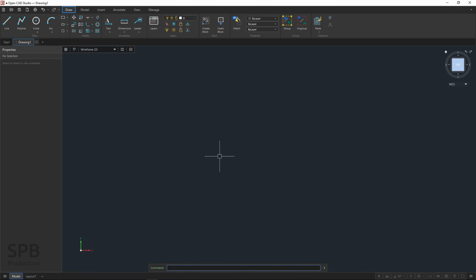Let me first show you, without the polar tracking turned on, if I wanted to create a rectangle from lines, I would fire up the line tool, I would click the first point, and then I would move my mouse and I would enter the distance. So I would enter, let's say 20, then I will hit tab and hit 0, so it will be horizontal, so 20 under the angle 0. Now I will move my mouse here, now I will type in tab 10, 90, so this is degree 90.